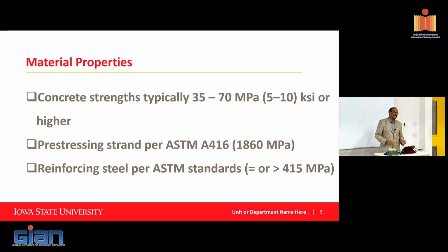For that reason, it's not uncommon to see even 60, 70 megapascal concrete for precast products. If you want to have higher strength, they could go up to 100 megapascal without much difficulty. So if for any reason you want a higher strength concrete, you talk to a precaster, they will be able to accommodate that.